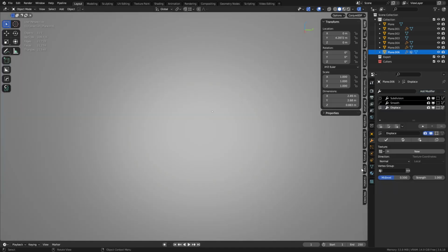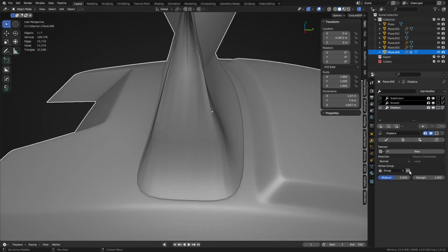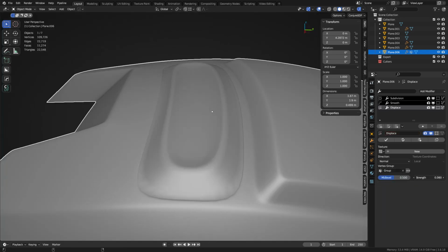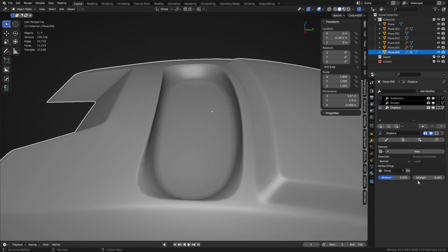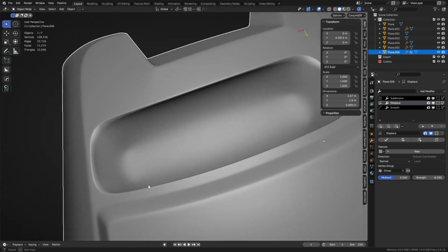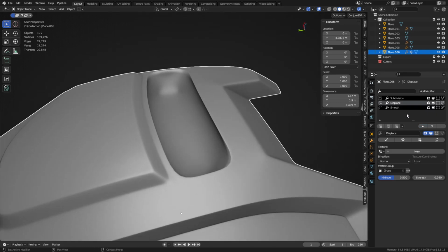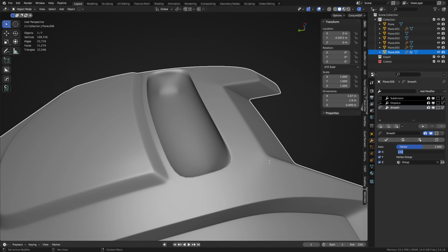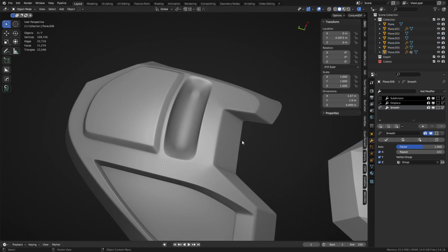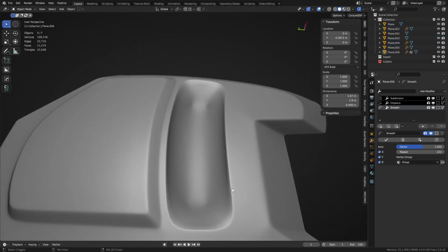I mean, you can do like displacements, right? And so displace right now, vertex group. You can set the strength values. You can do fun stuff like that. Maybe put this displace before the smooth and then push it down. And so the smooth will take effect on it the way you've set it up anyways. So let's see if that gives you a result you want. Yeah. So there's all kinds of cool little tricks like that all over the place, basically.